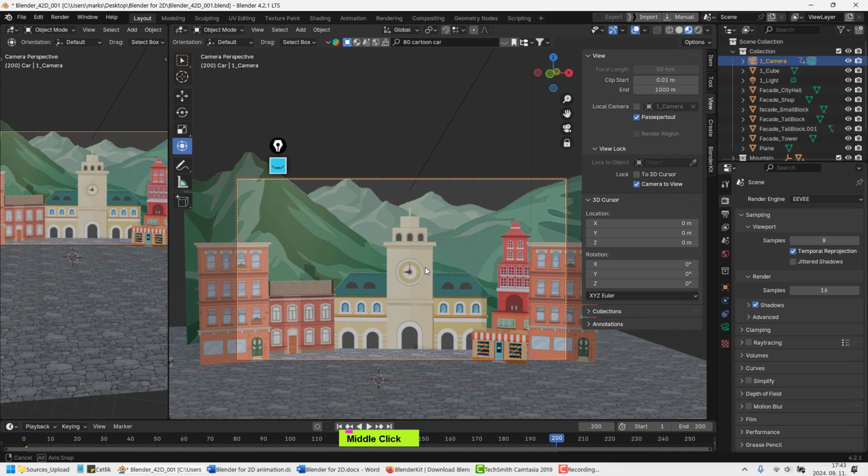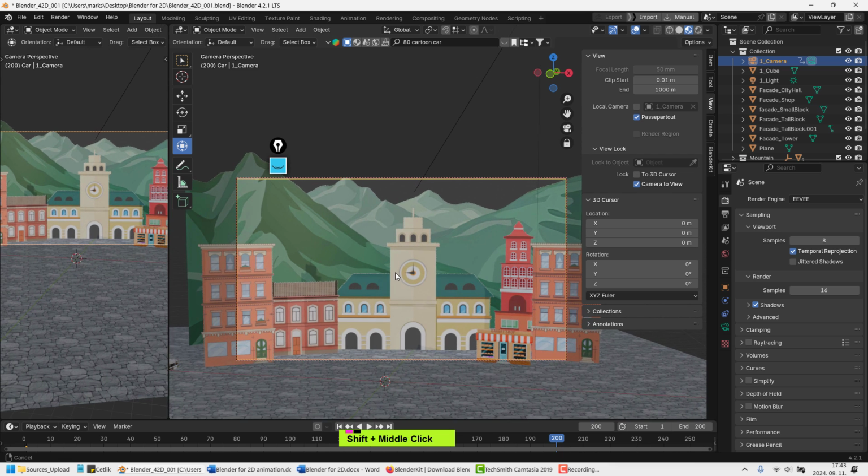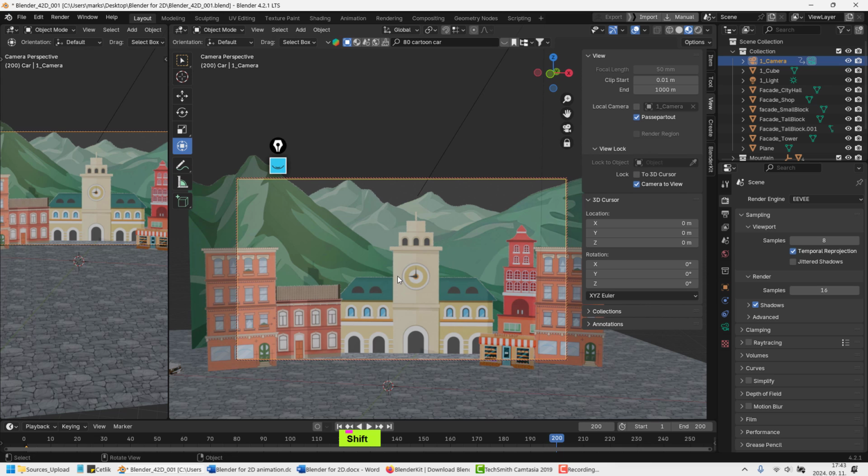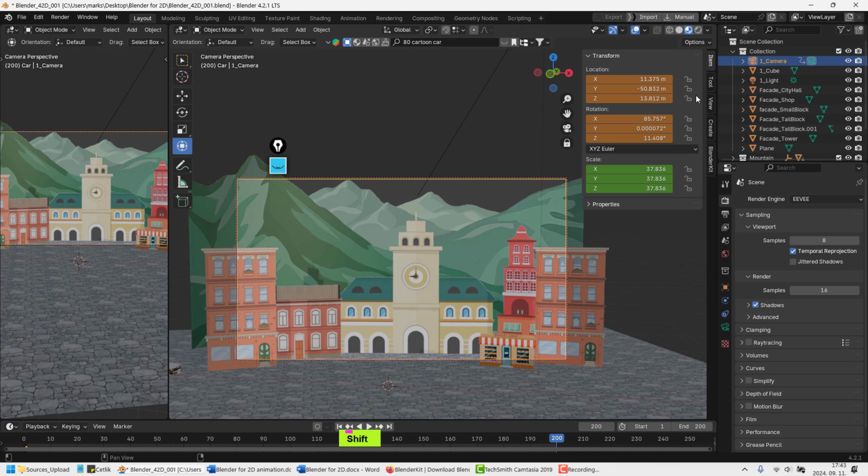Now, if I go back here, it shows that this new color is coming in. That means you have made the change, but it's not recorded. So it's not green. That means you have made a change. It's not the same as the first one, but there's something there. If you press I, it will place a key, and now the key is visible as well. So let me just elevate it a little bit. So now we have this animation.